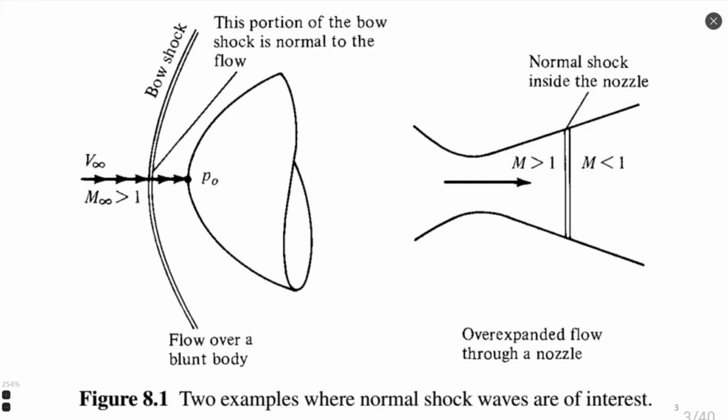They can also be separated into external shock waves, which are not limited by the size of the body but are caused by body and flow interaction, and internal shock waves, as you can see on the right of this picture. It's a shock wave which appears inside the supersonic nozzle.